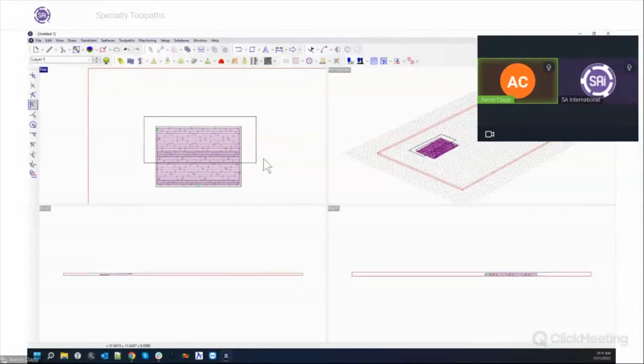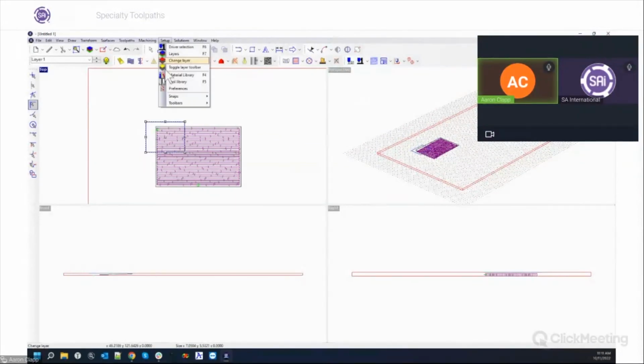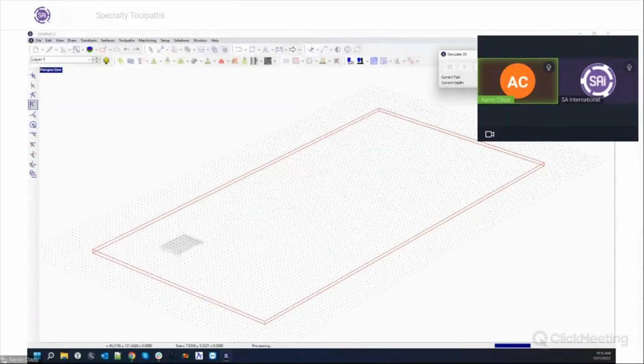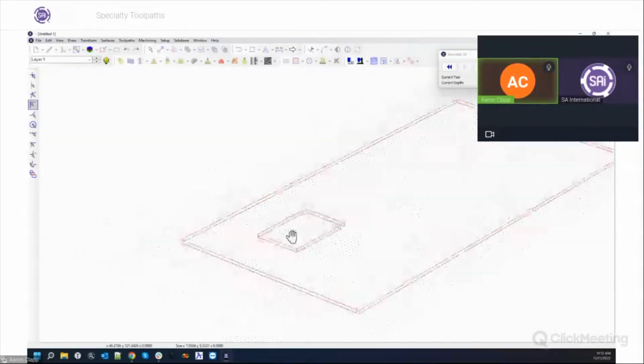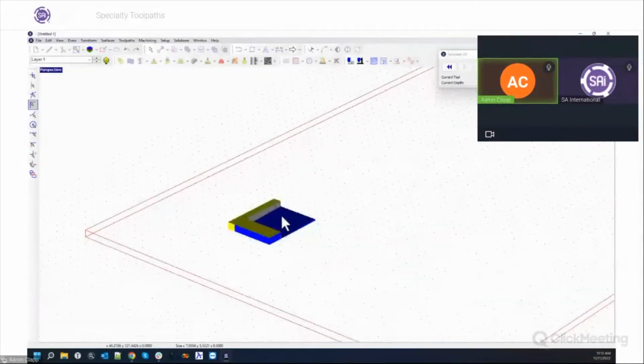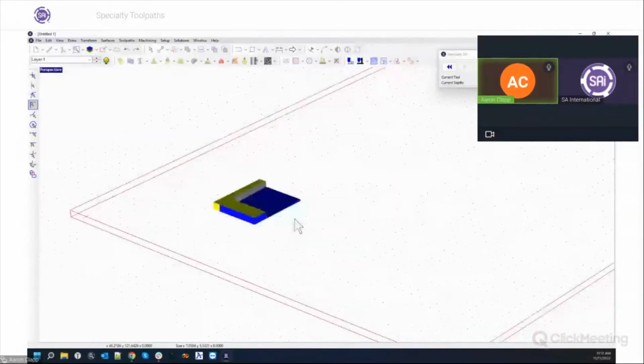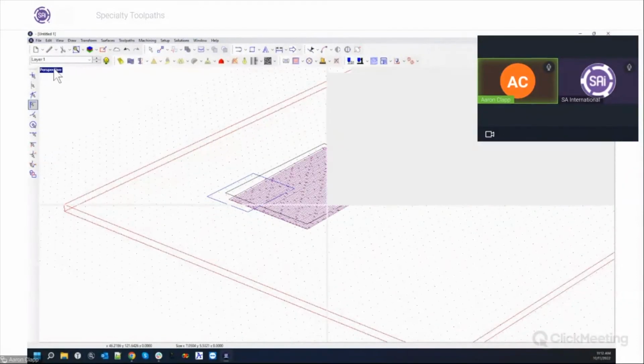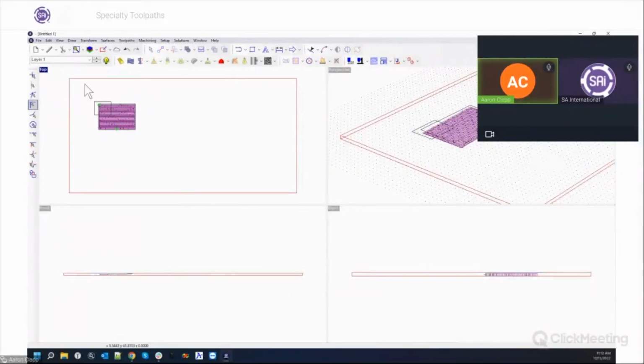So, perhaps maybe you want to preview this little section up here and just see how that cuts. You do that, and you can do this a couple different times. Now, obviously, it's not the most ideal, but this allows you to bump up your resolution much higher. So now we're running a resolution of 184, which is really high, but I'm only having to process a small piece here. So the processing works much faster. So now you can see when I move it around, it's instant. So I can go much higher on my processing if I selectively choose which areas I need to process.